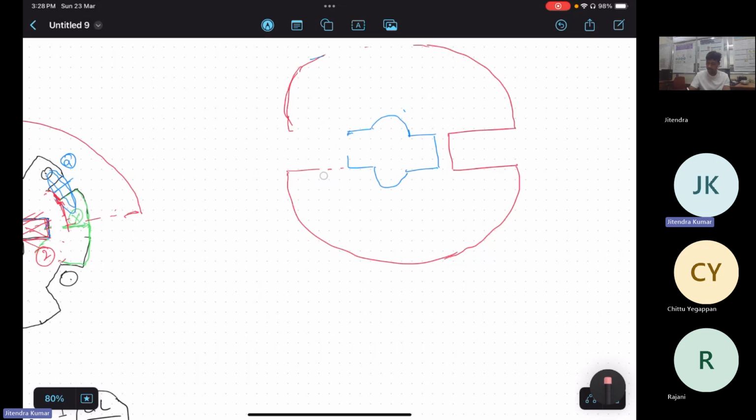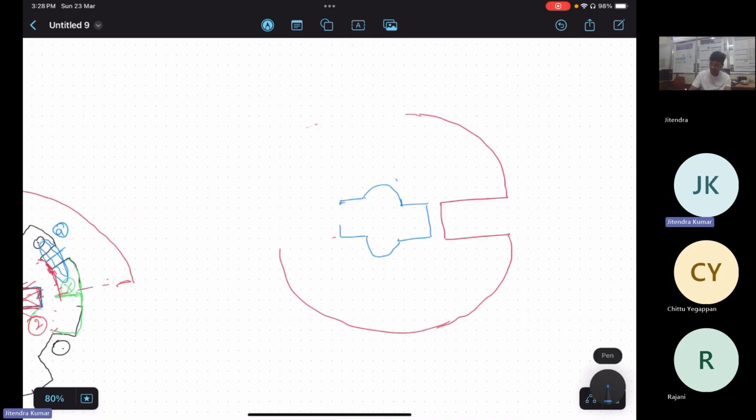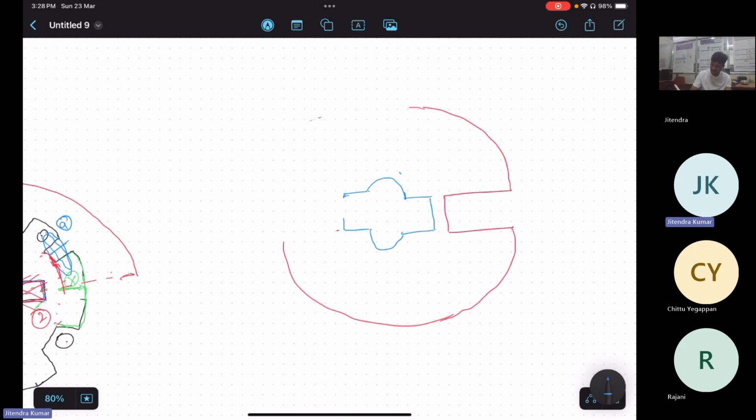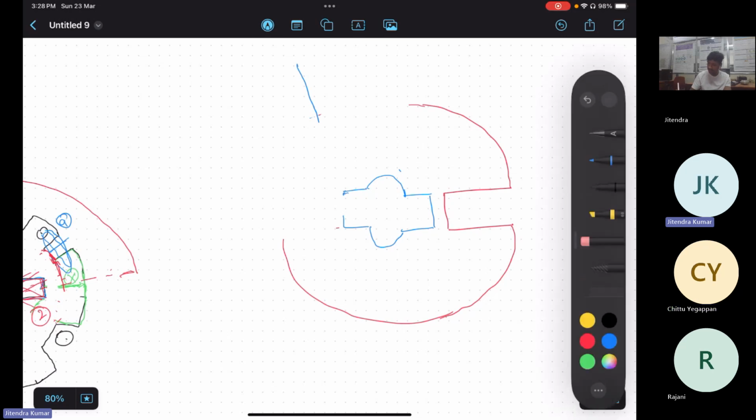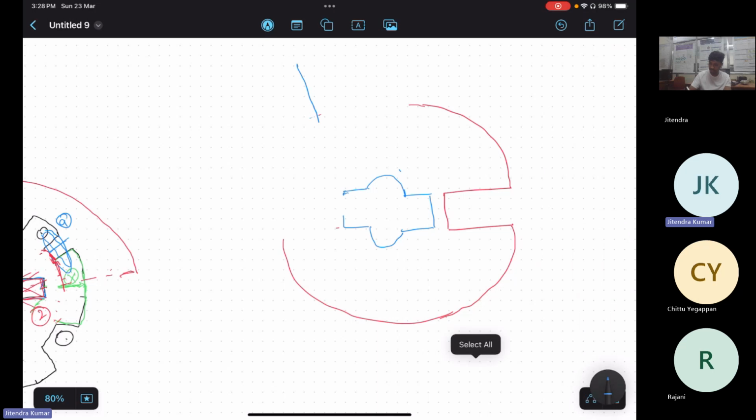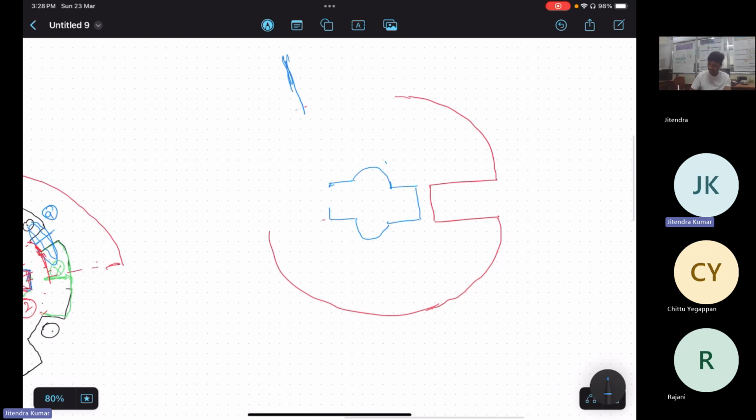So, Chitu, did you get why the same number of stator teeth and rotor teeth are not allowed? Yes, sir. Why? Am I audible? Yeah, you are audible. What did you ask, sir? Why are the same number of stator teeth and rotor teeth not allowed in SRM? Due to the magnetic locking. No, due to locking, it won't move ahead until the next unaligned position is there.